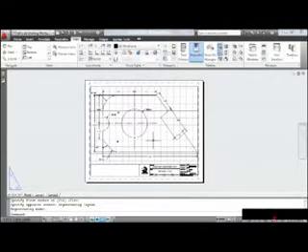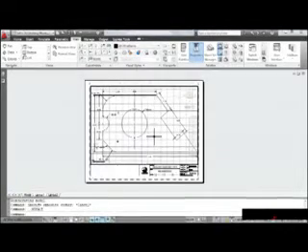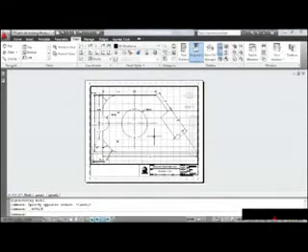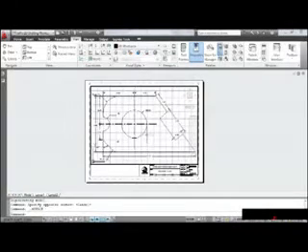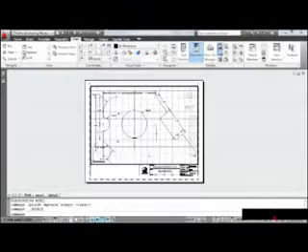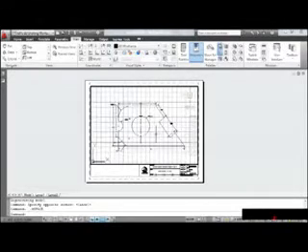A viewport is a lot like a window into model space. Watch this. If my cursor is inside the viewport and I double-click, AutoCAD gives me access to model space through the window. From here, I can pan, zoom, I can even work through this viewport. It's a lot like reaching your hand through a window. In fact, we'll adjust the plotted scale of this geometry by adjusting the zoom factor.